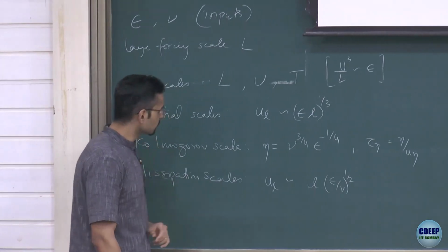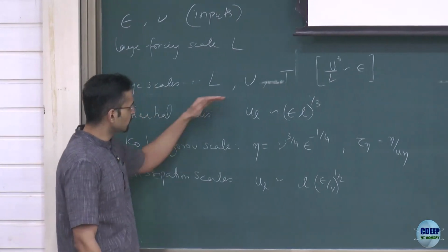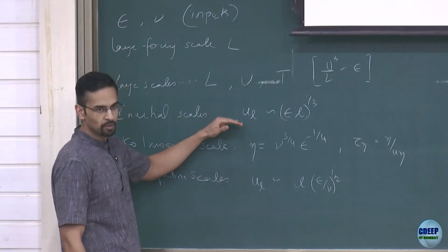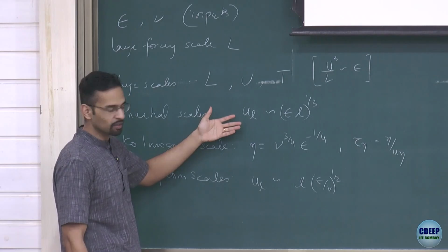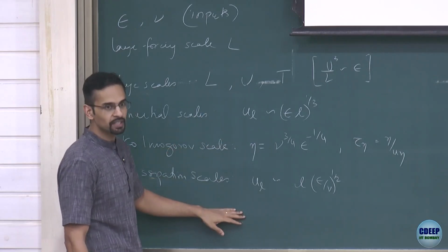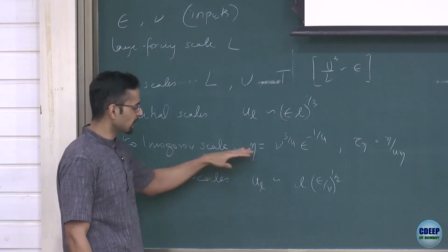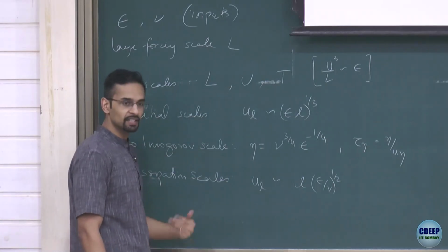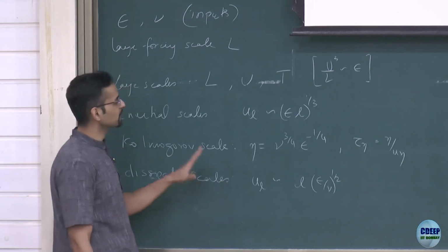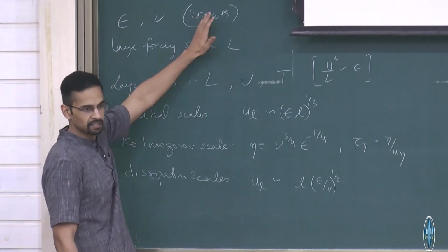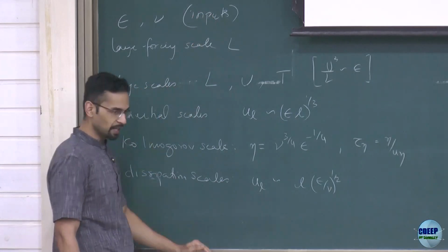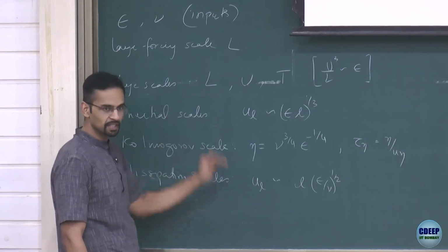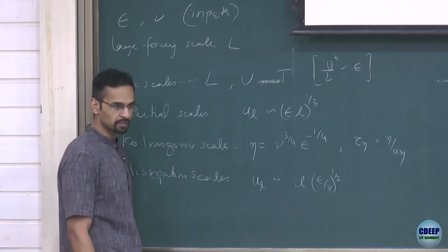And I think in the last class, what we showed is that yes, you can have a scale-dependent Reynolds number, which will be much larger than 1 above the Kolmogorov scale, showing you that the viscosity is not important, and much smaller than 1 below the Kolmogorov scale, right? And at the Kolmogorov scale, it is 1. And this whole range of scales is almost necessitated by the fact that I'm pumping in energy only at the large scales, right? And I'm able to dissipate by viscosity only at much smaller scales. And somehow the energy has to get transported to the small scales.